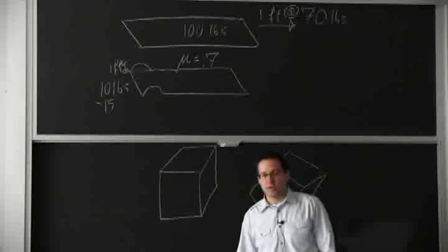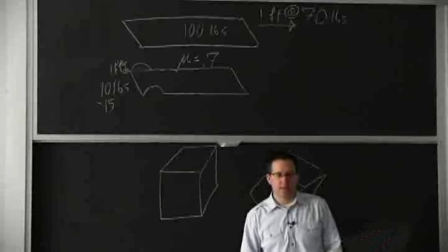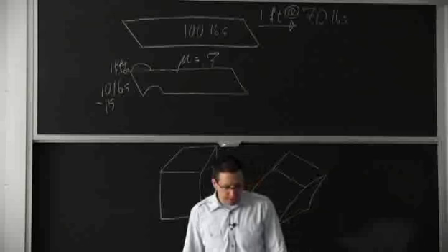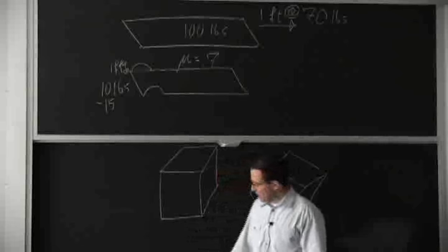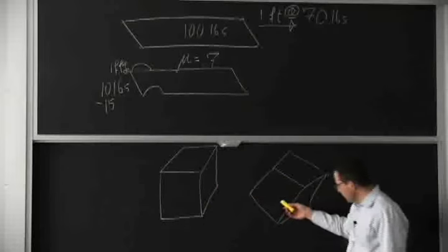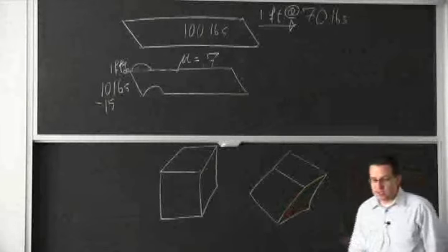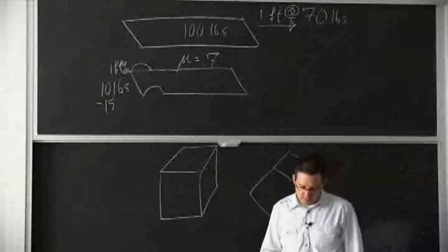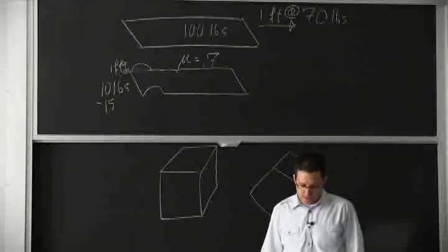In forming operation, a lot of times we know them by the geometry of our load applied. So it's actually simpler than what it looks like here. Here we have formulas where you have the XX and YY and all these stress components. You take them from here, you take them from this orientation. At the end of the day, they'll give you the same value of I1, I2, and I3. And therefore, the same values for the principal stresses.